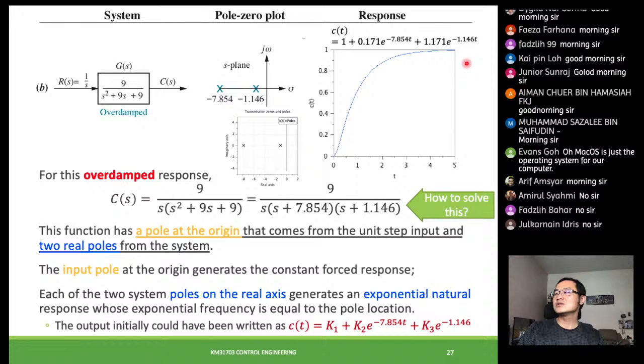the only difference is at the beginning, right? So in the second order response, it will still curve up in this way, right? Whereas for the first order, it will directly go up and settle, right? That would be the characteristic of the curve that you know. So from that, you will know whether the system is first order or second order.